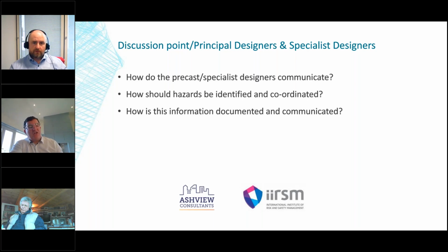I think as design risk management goes, having a flow between design, construction, and future maintenance, and anything that you document is very important. As a design risk manager, you're documenting where this is going. If something can't be designed out, has it made it to a construction risk? And if it's a construction risk, has it made it to a residual risk for future maintenance? That is very clear about ownership around that, and possibly getting input from a designer on that. So your drawings, workshops, DRAs, obviously the operation, safety file and operation and maintenance manual. So that's the construction work, but then when it's handed over to the duty holder, making sure that the right information is there for the right people to use on the maintenance of the building.